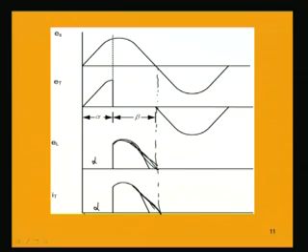So, if we consider the input waveform of ES, we are getting the output waveform for only a small portion of the input wave. So, we are basically controlling the power input to the resistance, because we are not allowing the whole input voltage to be supplied to the load, we are only applying a small portion, and the current is also present for a small portion. So, the power, which is voltage into current, will also be present only for a portion of the whole input cycle.